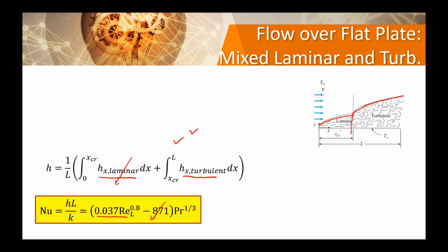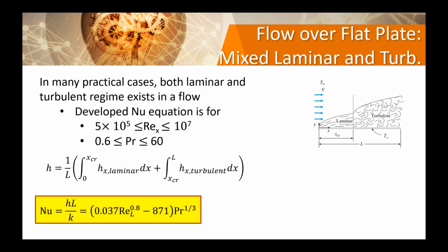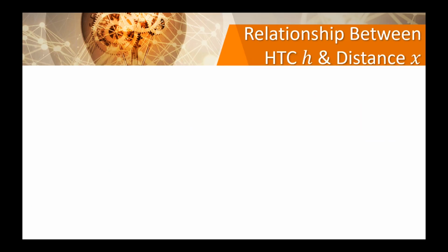So if for any practical reasons this laminar portion was negligible, then it becomes a fully turbulent boundary layer. So anyway, you may not want to simply shave off the laminar part, because there's a rule to whether you can omit it or throw it away or not. Okay, that is all to it, right? The Nusselt number for all these flow regimes.